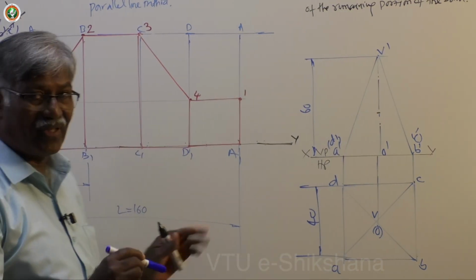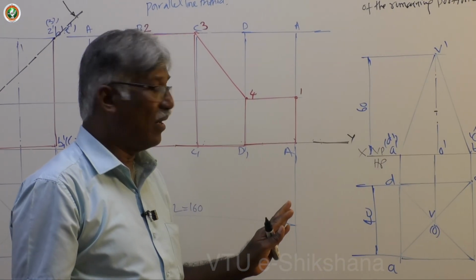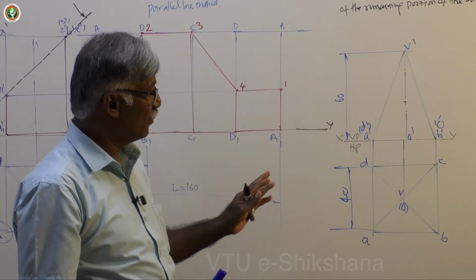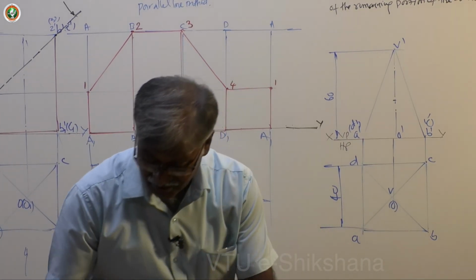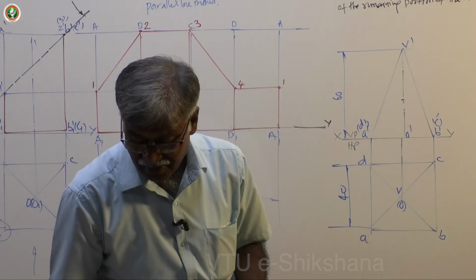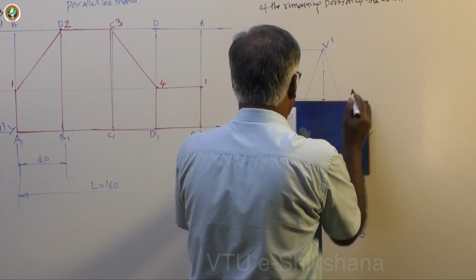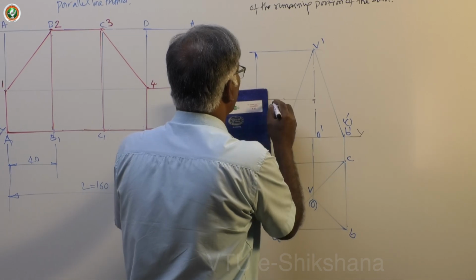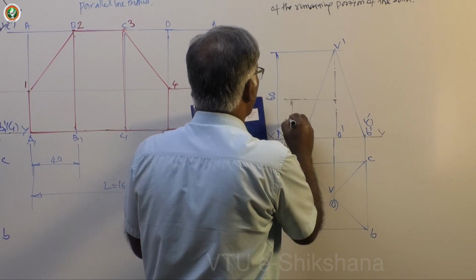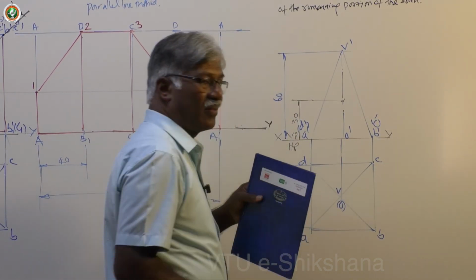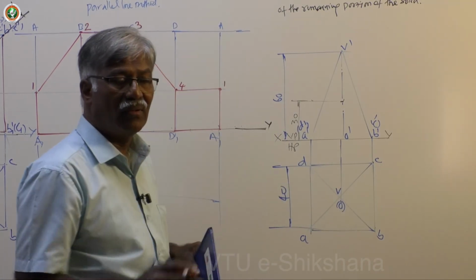Now you have to keep everything in light lines. Now take the section plane. Draw the section plane with 45 degree inclination. Now select this midpoint. This is 30 mm. This is the point, you can say. Now draw a 45 degree line.